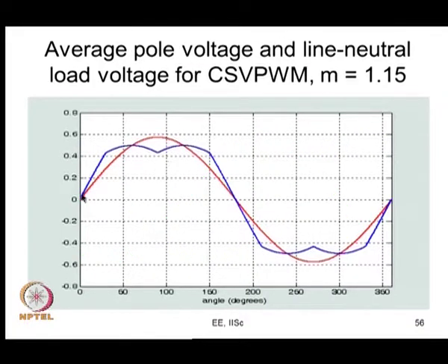Now, what you have here is this VRO average, it has a peak value of 0.5 VDC and this is 0.577 VDC. Again at the expense of repetition, I would say that whatever triplen components are here, you subtract them, and you are actually getting this now.